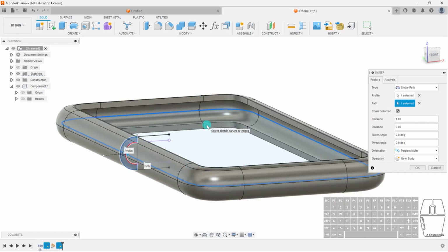So sometimes if the 3D body doesn't allow you to create the sweep, you have to think, how can I replicate this 3D body path using a sketch instead? In this case, we can project the bodies. If maybe say there aren't any clear defined edge, then you may have to use splines or other sketch tools to create this shape. In this case, if you created a rectangle and filleted the edges, you would also get the same shape. So I'm okay with this.